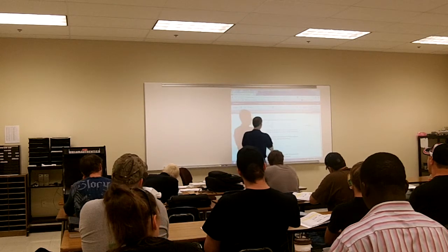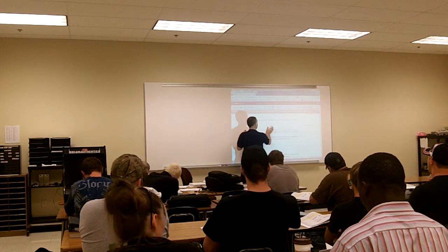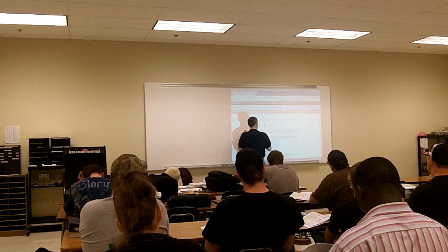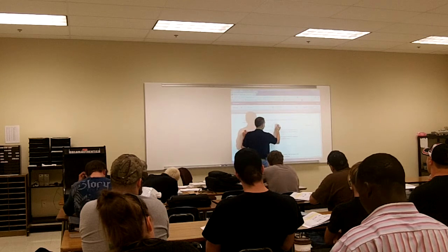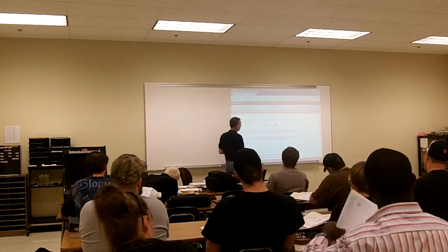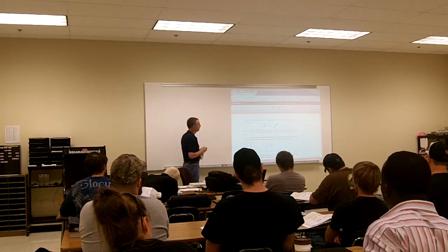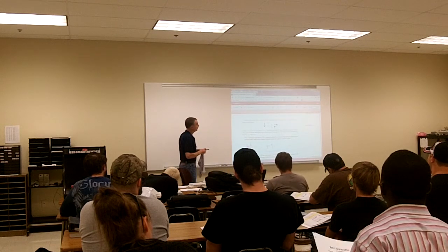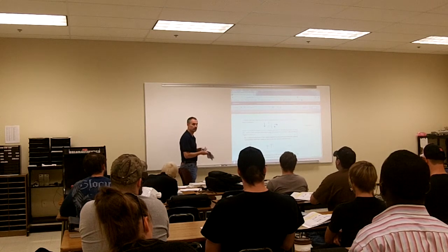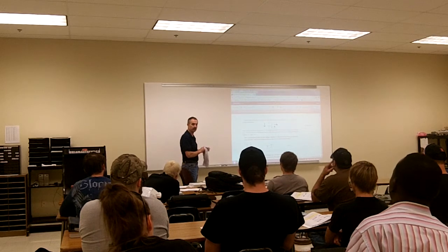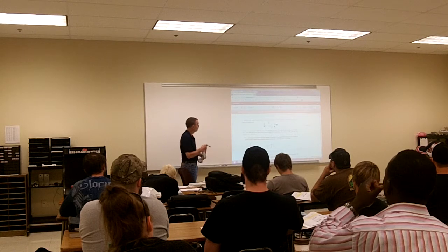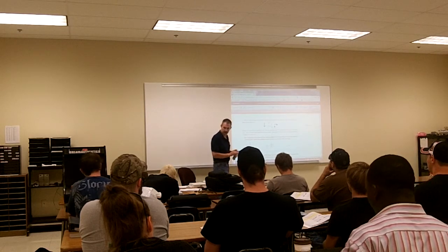Let's do it this way. Let's say I'm in new trouble. My current went down. We'll do a natural failure here. So if my current goes down and my voltage is constant, my resistance had to do what? Go up. And which way do resistors typically fail? I think it was one of our questions, wasn't it? Wasn't it one of our question packets on the failure of a resistor? Yeah, but if the resistor goes bad, I think you just went over that in class.